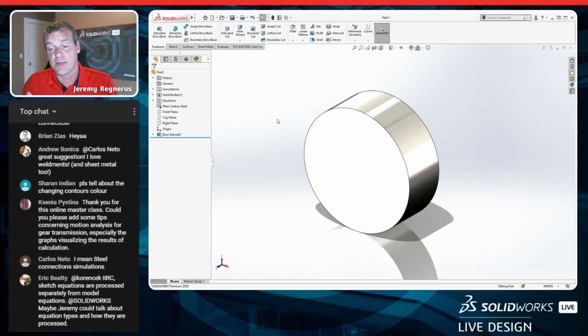So we've got this done. The next thing we need to do is start creating the tooth for our gear right here. You'll notice that when I extruded this, I did it about the midplane, and that wasn't done on accident. Everybody in live design has taken time to talk about design intent and capturing that. And I, like everybody else, can't emphasize how important design intent is.